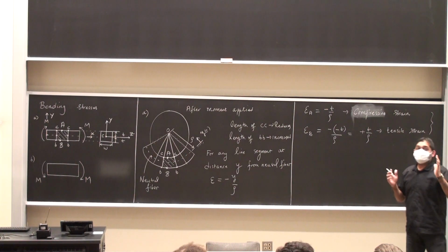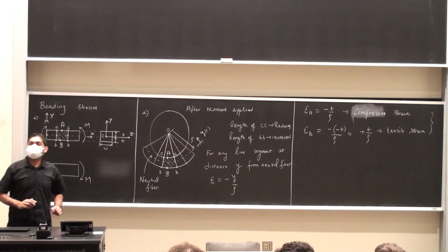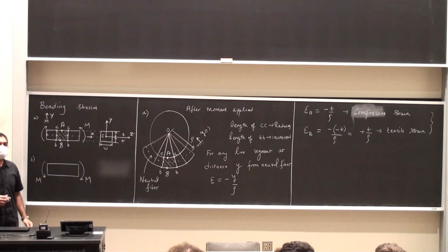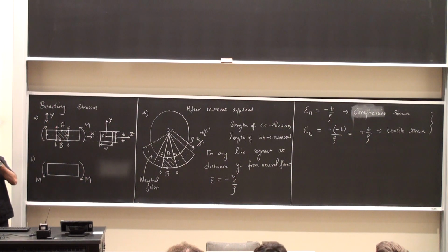So, okay, what is the direction of my bending moment? That is the sense. What's the directionality? So let's choose this guy. What is the direction of this guy? There are two things for a moment, sense and direction. Sense is clockwise or counterclockwise. It has to be accompanied by a direction. Is it into the page or out of the page? Into the page or out of the page, right? So it can be either that or this.